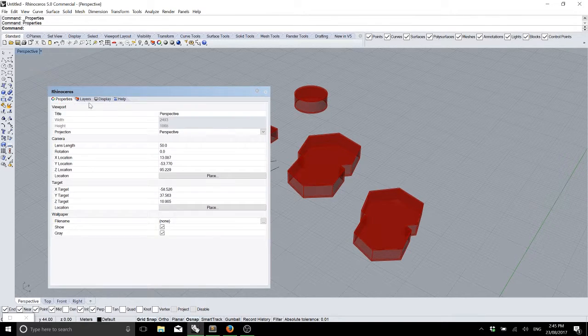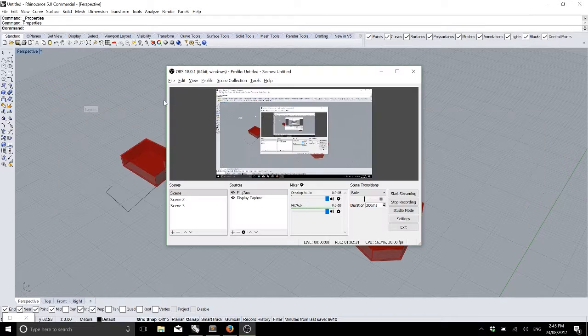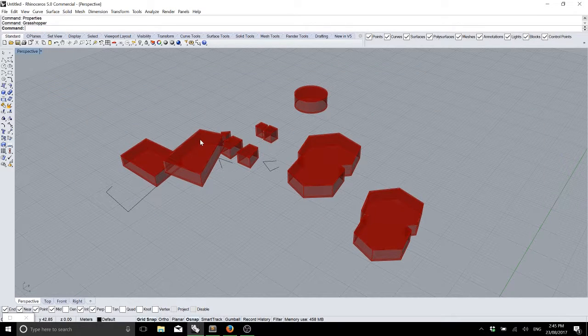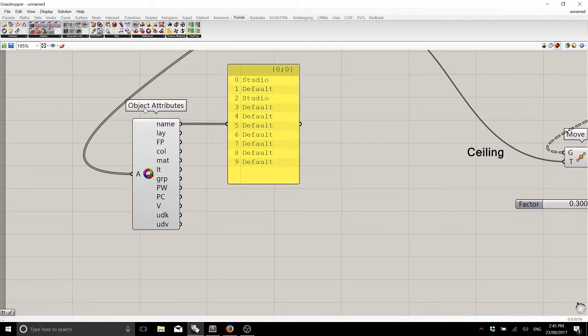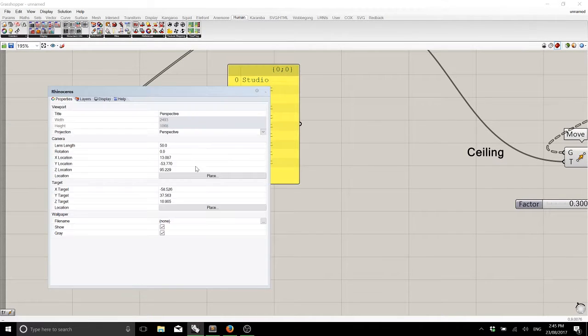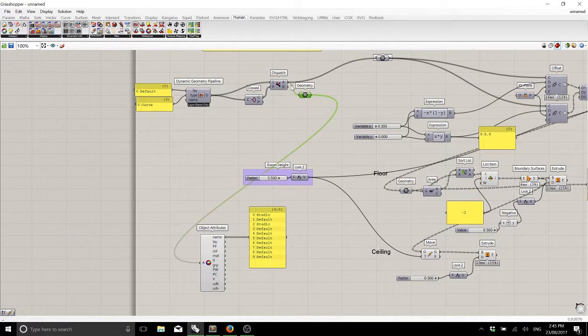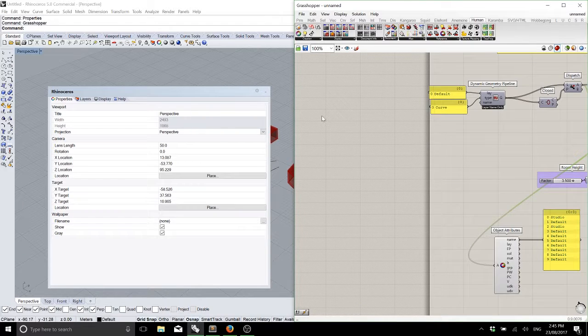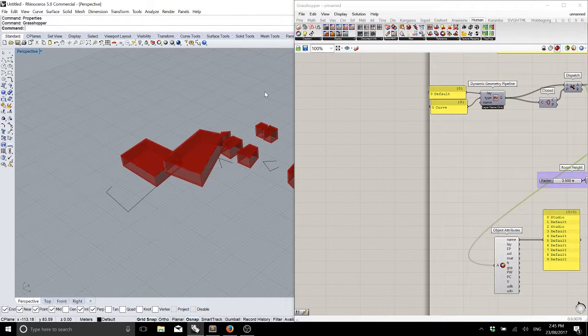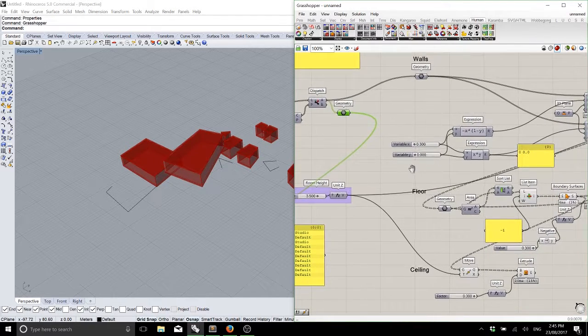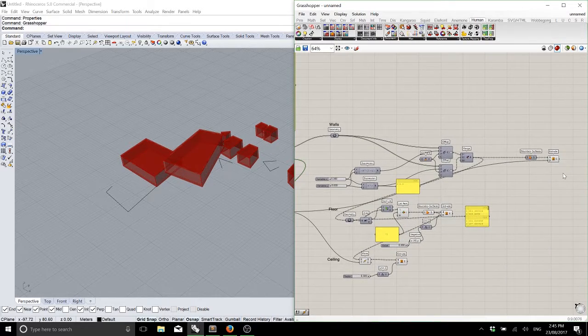What did you attach to Human? I got from Human a component called object attributes. What is going into that is the geometry after it was dispatched, because we don't want the curves that aren't closed. Remember? Yeah. We could actually plug those curves that aren't closed into the wall output and still have them make walls, like so. Actually, you probably want to do this.